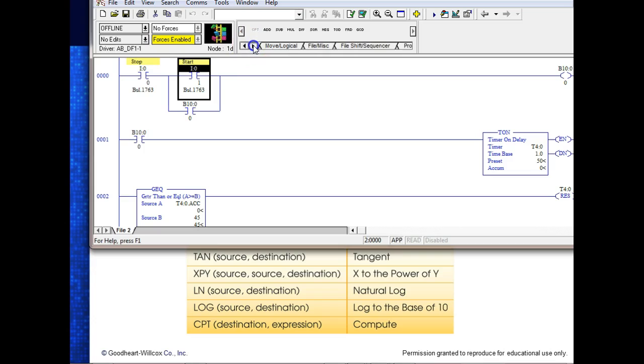Then over here we should have another one that's got ASCII, micro high, trig functions. So this guy here does not have any trig functions. See, they're all grayed out. So this PLC, advanced math, has ABS, SWP, DCD, and ENC. Is that in there? That should have been in that first list.